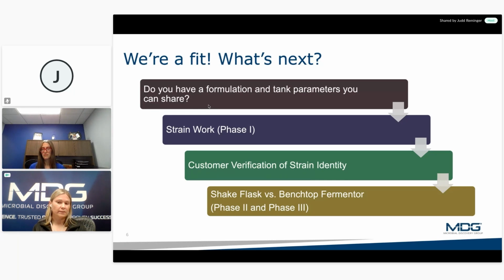There, we usually like to spend about 6 weeks. Those are in the 5-liter benchtop fermenters. Here we are able to do a little bit more control, looking at our pHs, our dissolved oxygen, our aeration, our agitation, really looking to scale down from our big fermenters to labs so that we get the best idea of what to expect when it goes to the commercial floor.